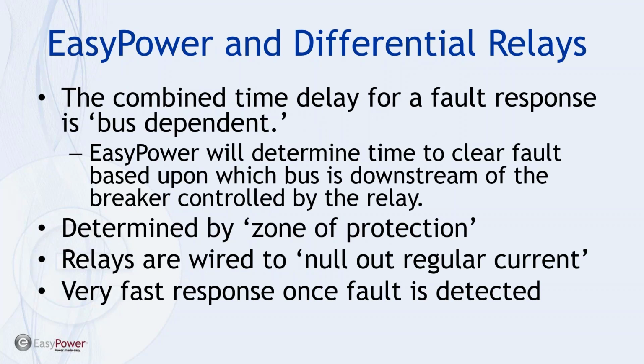Okay, now in EasyPower, the way we simulate a differential relay is we calculate the time delay that the relay will exhibit for whatever difference criteria we've determined for our system. And then EasyPower will determine how that time element will affect the incident energy calculation, assuming that's the system that clears the fault.